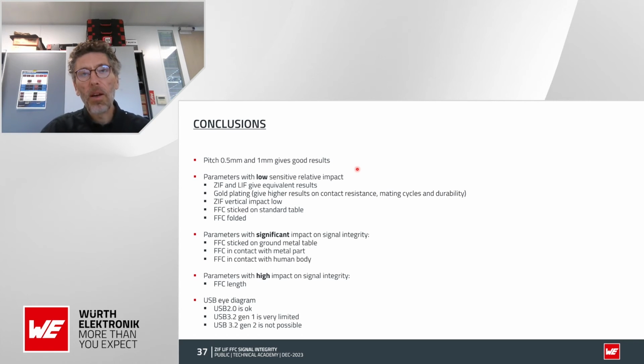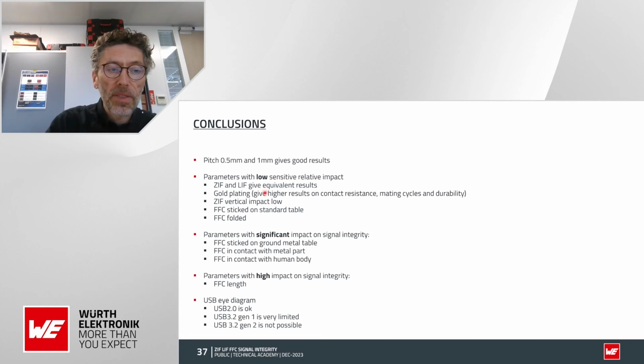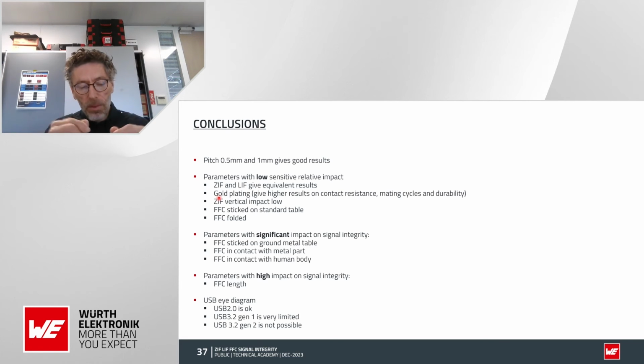length, of course, up to 3.5 gigahertz for the bandwidth, for the smallest FFC. Parameters with low sensitive relative impact: the ZIF and the LIF are the same. Gold plating and tin give the same result in the beginning, but if you want to manipulate it and do a lot of mating cycles, then use gold. ZIF vertical has no difference with the horizontal.